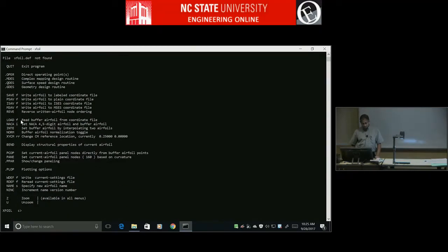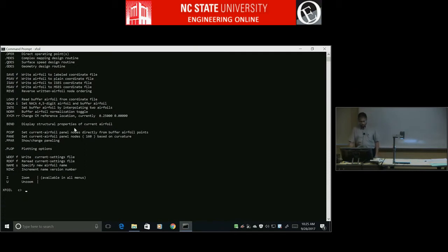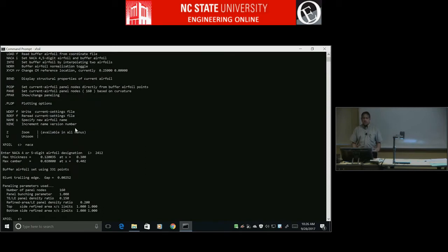Maybe the best thing to do now is to say NACA. There is an option here saying NACA and then I. That means you can type NACA like 0012 and it will create a 0012 airfoil, or you can type a 5-digit one like 23015. So there are a couple of ways to do this. You can say NACA, enter, and then it will say enter 4-digit or 5-digit. Let's just say 2412. Now it will create the NACA airfoil, and it's done the paneling.